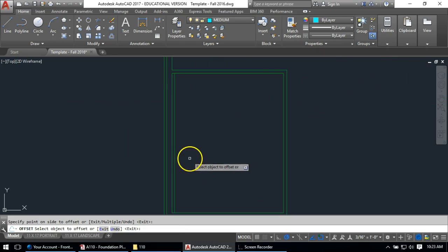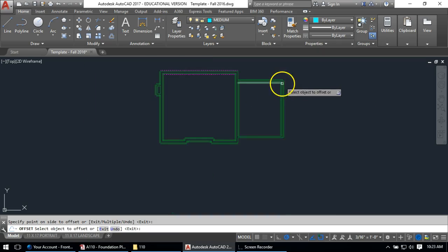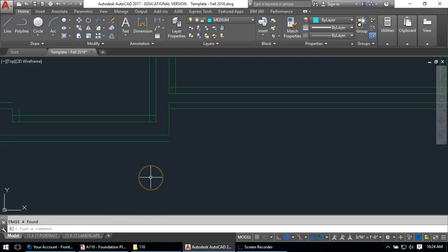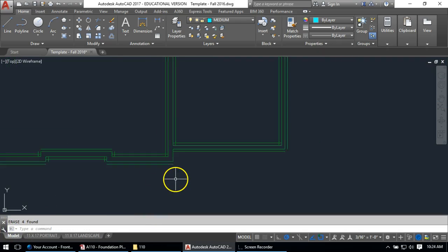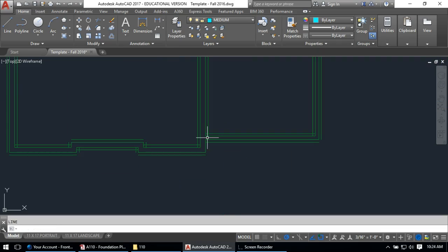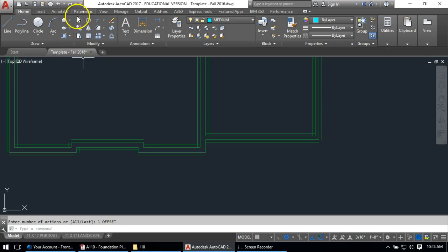Now these foundation walls are only 8 inches thick, but you'll notice on the drawing that the footing width is only 1'4", so we pretty much still have the same 6 inches that we can offset here, and here, and here. Let's see, 12, 4, 4. Actually, if I do my math right, that's only going to be a 4-inch offset. So let me undo that. I'm going to hit U, enter, and just undo. Undid too far. Redo. There we go.